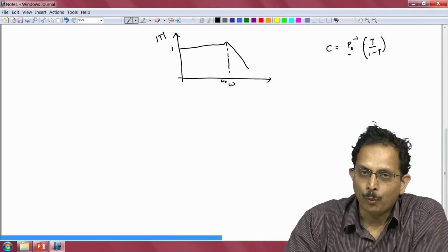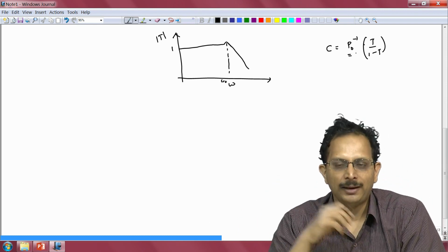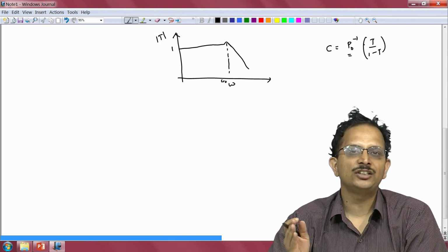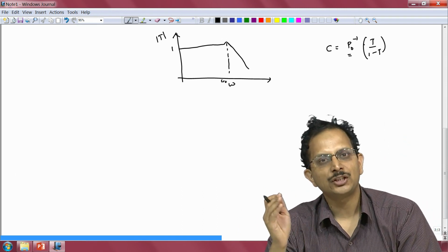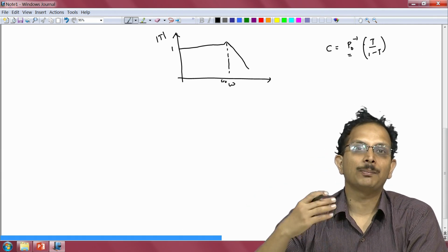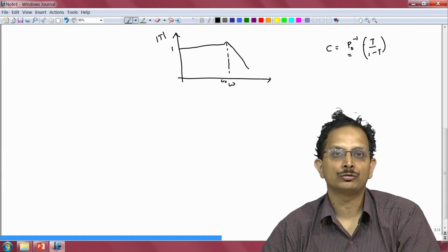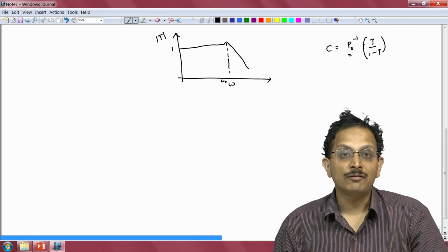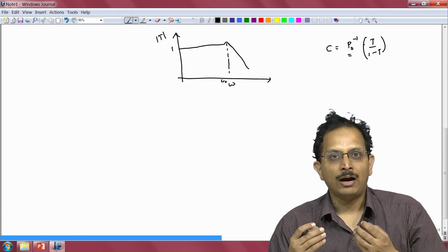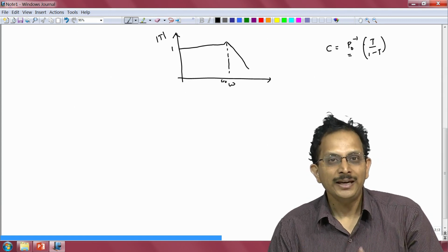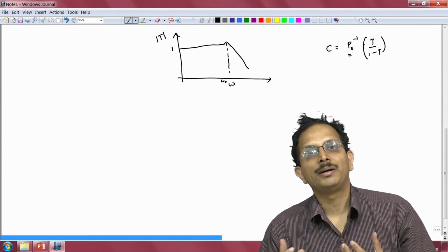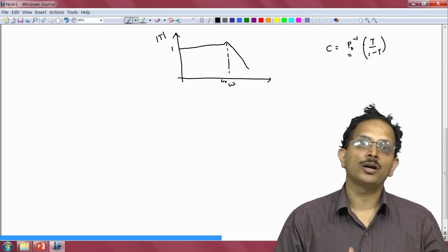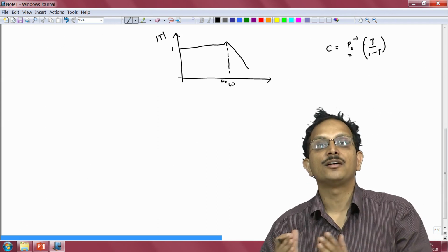Now when we experimentally obtain the plant transfer function, we can imagine that when the frequency of excitation to the plant becomes larger and larger, then the response of the plant to excitation at those frequencies correspondingly becomes very small. Therefore at very large frequencies, our plant's response will be buried in measurement noise. Therefore the uncertainty associated with our plant model will be larger at higher frequencies.